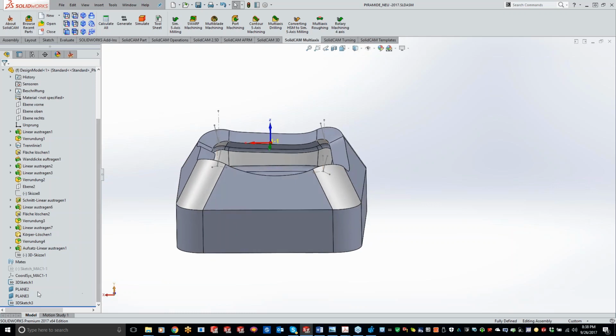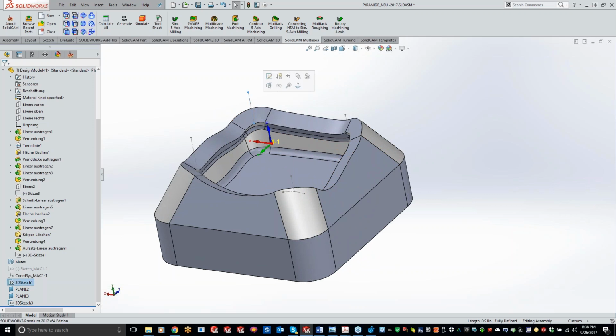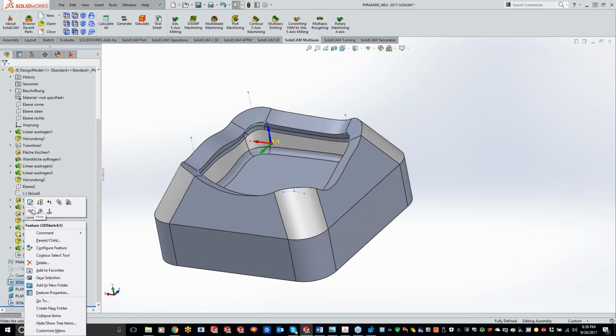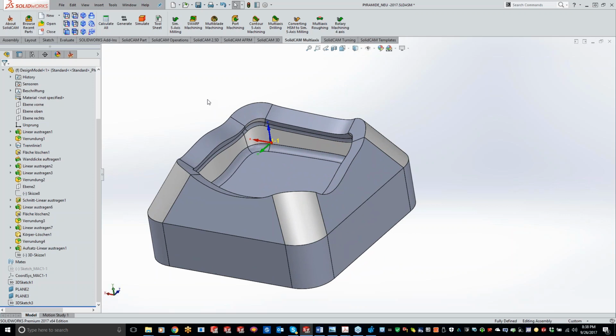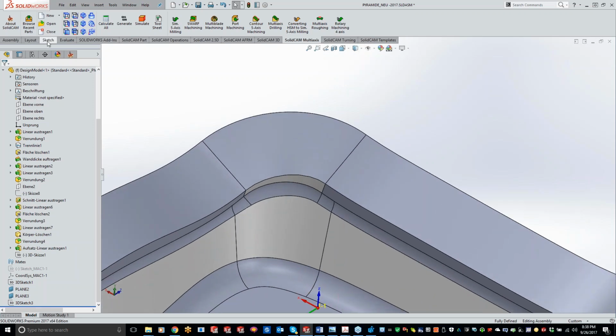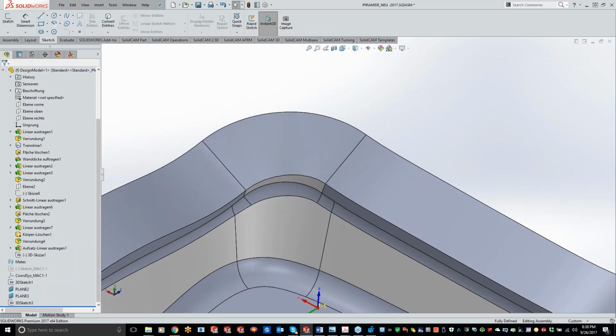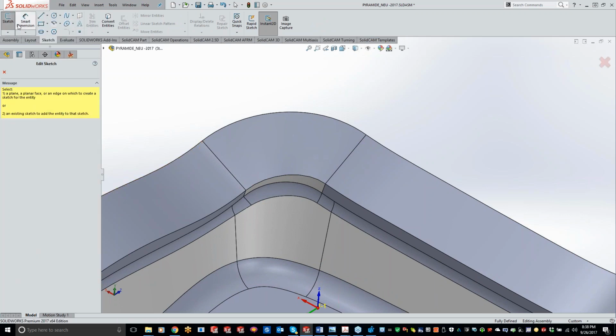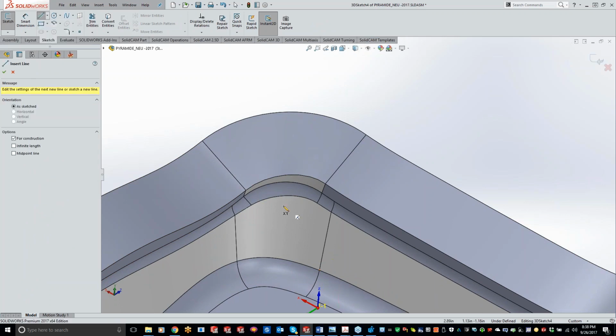Yeah, absolutely. So let me just go through and hide what we previously did here. And where's that line pulling from? Okay, so kind of starting off from scratch right here. Basically, all we did is add a couple of lines in here. So if we just do one corner, one corner would be enough to take care of it. So I'll just do a center line right here, and I need to do a 3D sketch. Grab that center line here.